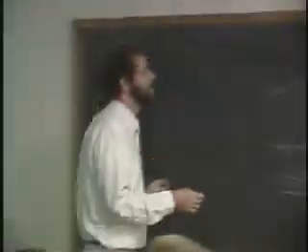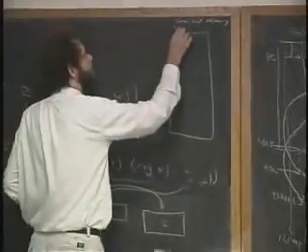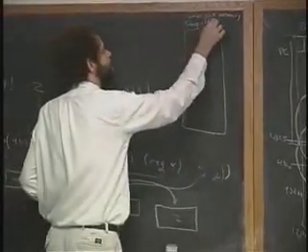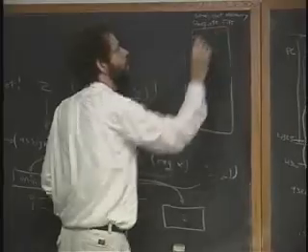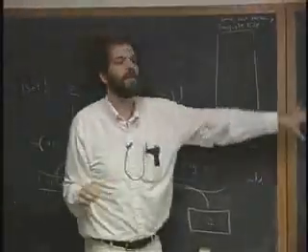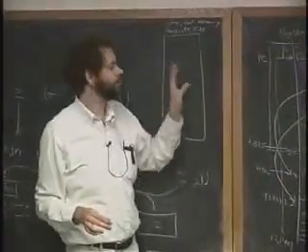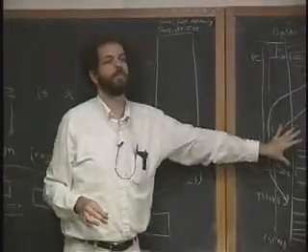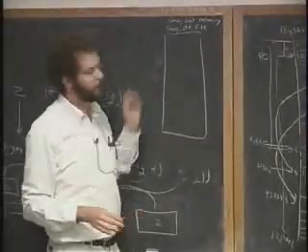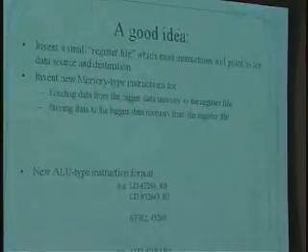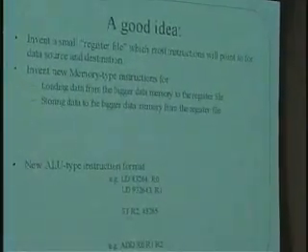And what we will call this small, fast memory system is the register file. And here's where I reintroduce the word register. But hopefully, it's no longer just a place with pointers into the main memory. It's a place where we shuttle data back and forth, the bookshelf to the library of the big, slow system. Okay? So inside of the processor, a great idea will be, instead of having these long words, remember the instructions had to be very wide, in this case, we're actually going to make this memory incredibly small.